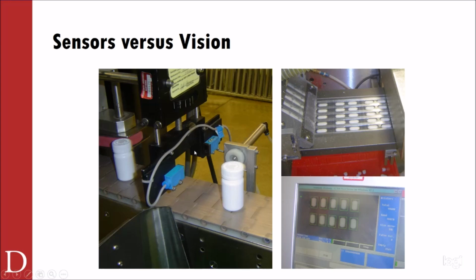So as an example here, this is a sensor, a picture of an emitter and a receiver on a sensor. And what this sensor is doing is it's sending a beam. This is kind of like the sensor on your garage door opener at home. But in this case, if that lid isn't screwed down all the way, guess what it does? It breaks that beam, right? It faults, it kicks that thing out is what it does.